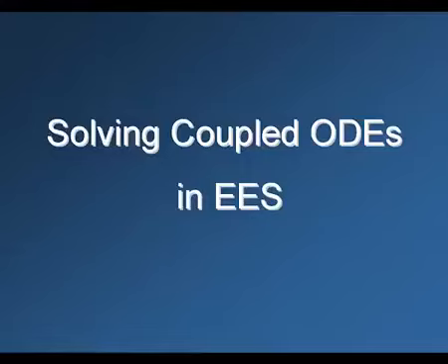Systems of ODEs occur in the solution of many transient problems. In the previous video, we looked at using the native ODE solver in EES to numerically solve a single ordinary differential equation. This was accomplished using the integral command, which is shown here. Multiple integral commands can be used together to numerically integrate a system of coupled ODEs.